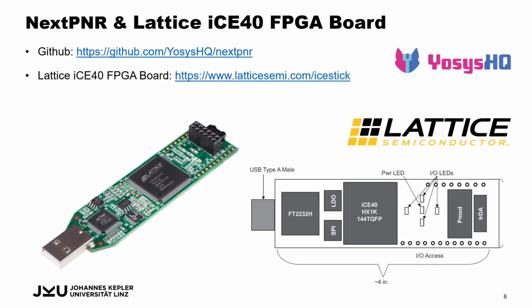As I said, we also have nextpnr in the Docker container, so we can, for example, flash a Lattice FPGA. This is also quite interesting because you can simulate your Verilog design, of course, with GTKWave or Surfer, and you can also double check your hardware stats with Yosys after synthesis.